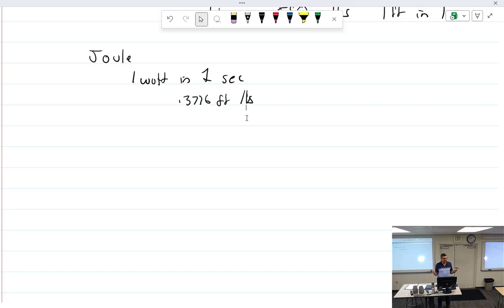So if we have our ohmmeter on the times 10,000 scale and we're hanging on to it, you're going to see a reading on there. When you have it on that scale, try not to touch. Otherwise, you're actually creating parallel circuits because it can measure you and the component you're testing. I also see a lot of you, when you're measuring your circuits and I ask what the amperage is, grab onto things and hold them, and that's fine for now. You're going to want to break that habit eventually, but you won't need me to tell you when it's time.